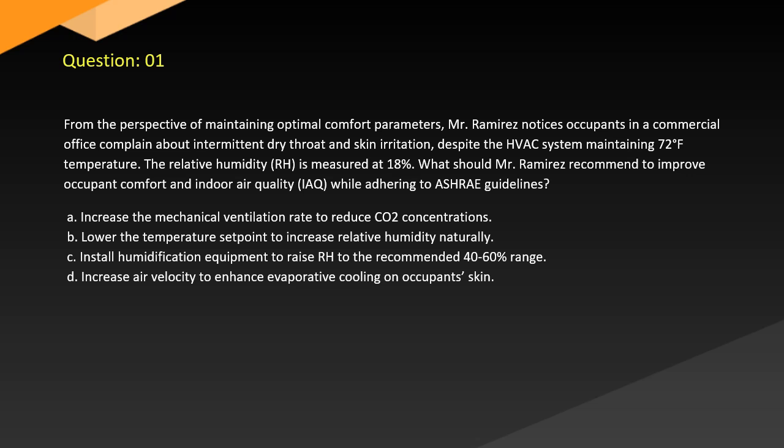A. Increase the mechanical ventilation rate to reduce concentrations. B. Lower the temperature set point to increase relative humidity naturally. C. Install humidification equipment to raise RH to the recommended 40–60% range. D. Increase air velocity to enhance evaporative cooling on occupant skin.